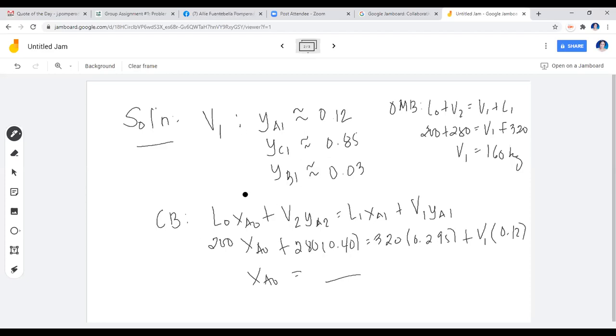But this problem cannot be solved purely using only the material balance equation. It is anchored upon the equilibrium diagram, the one that we base the composition of the extract layer. So the key in solving this problem is really using the principle that the two streams leaving, referring to the raffinate and the extract, are equilibrated, and their connection can be taken from the equilibrium diagram.